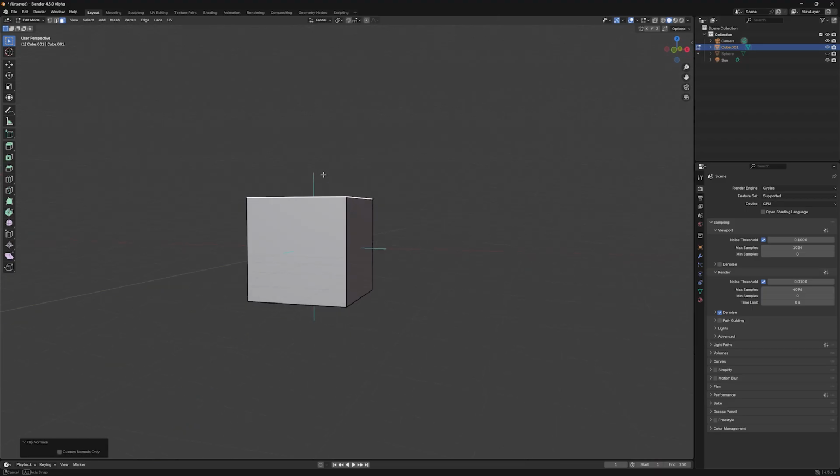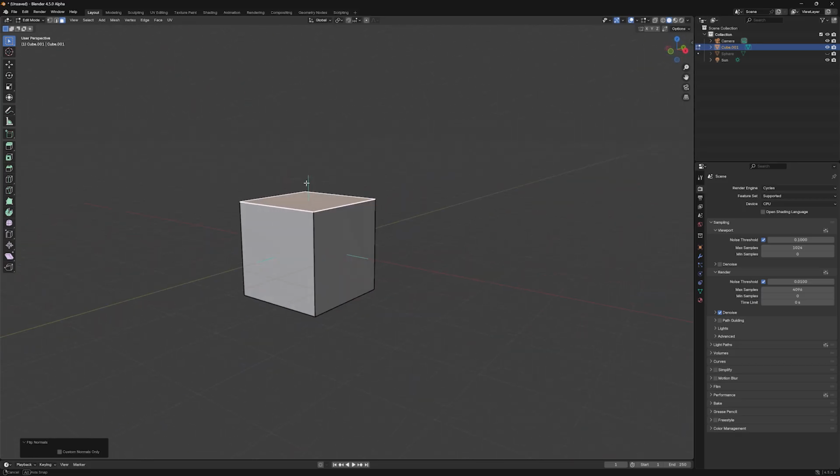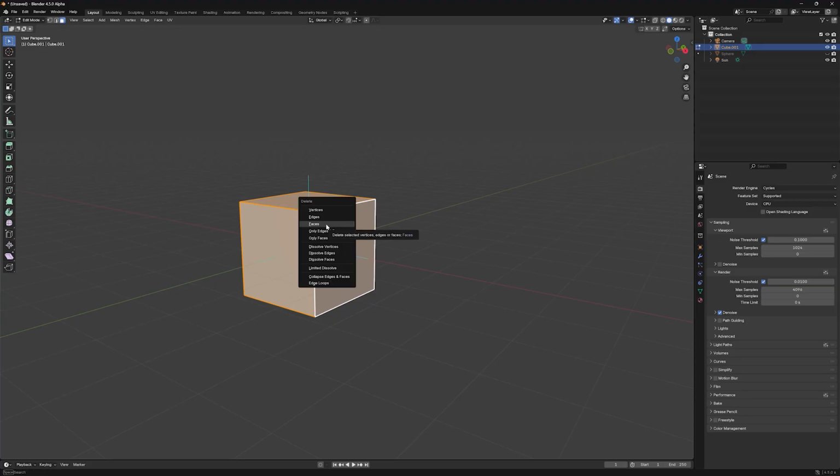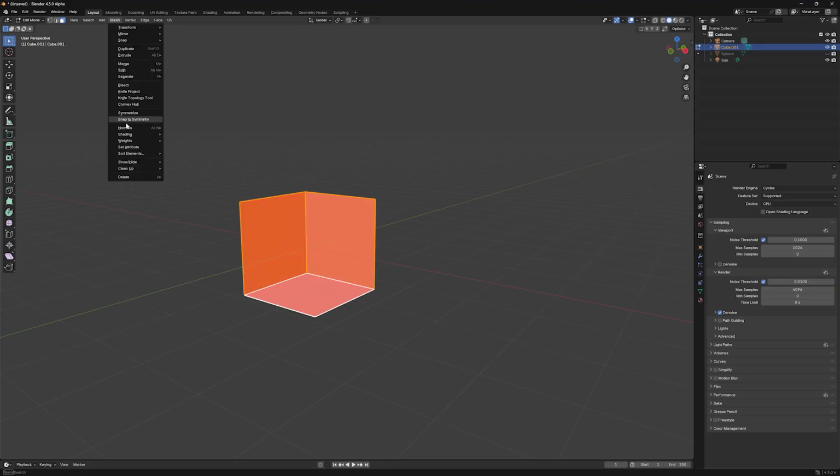Another scenario where flipping the normals can be useful is where we want to use what would normally be the inside of a mesh as the outside. For example, a popular subject for modeling is an isometric view of a room where only two walls and the floor are showing. The easiest way to achieve the walls and floor is to start with a cube and delete three of its sides. But what remains in view are back faces, which can easily be switched to front faces by using the flip operation.